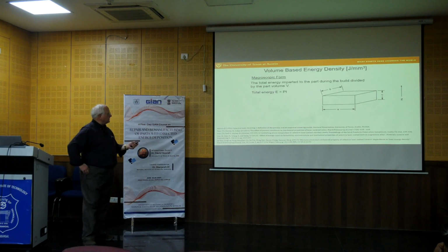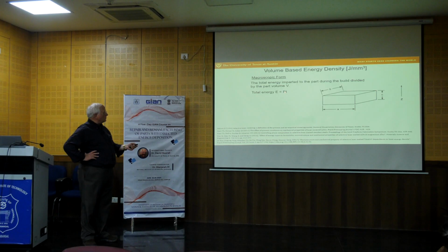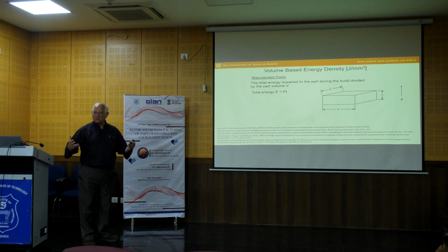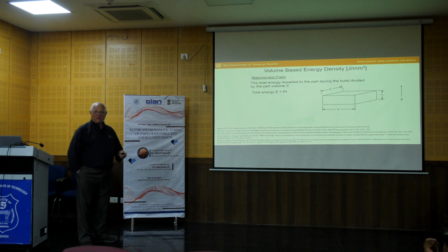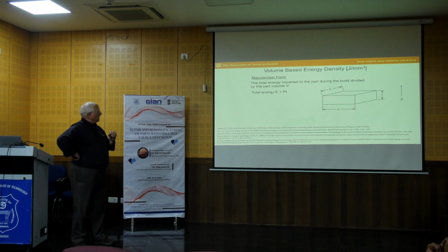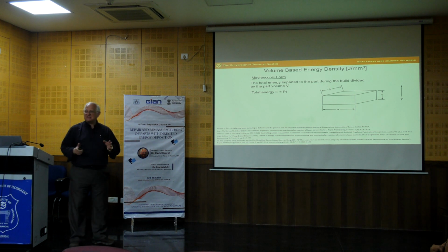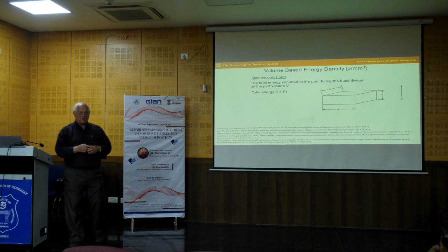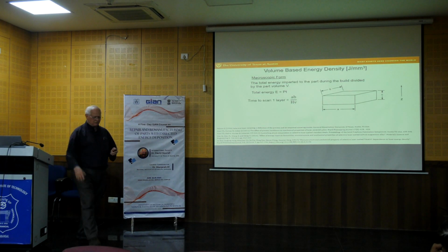The total energy that is deposited during this build would be equal to the power of the laser or the electron beam, or I guess it could even be the power associated with the arc, times the time that the part is being built, right? So the power for this equation is easy. The question is, how do we calculate the time that the beam is on and depositing energy? That's the hard part of the calculation, but it's not too difficult.